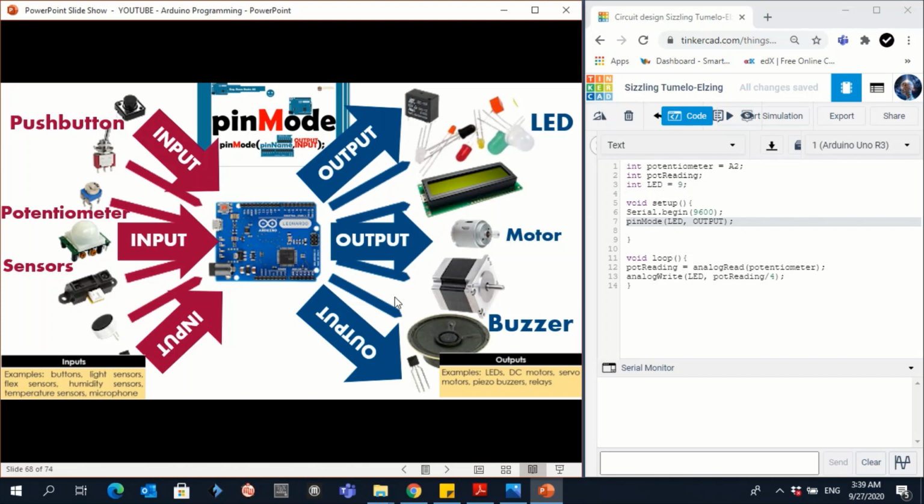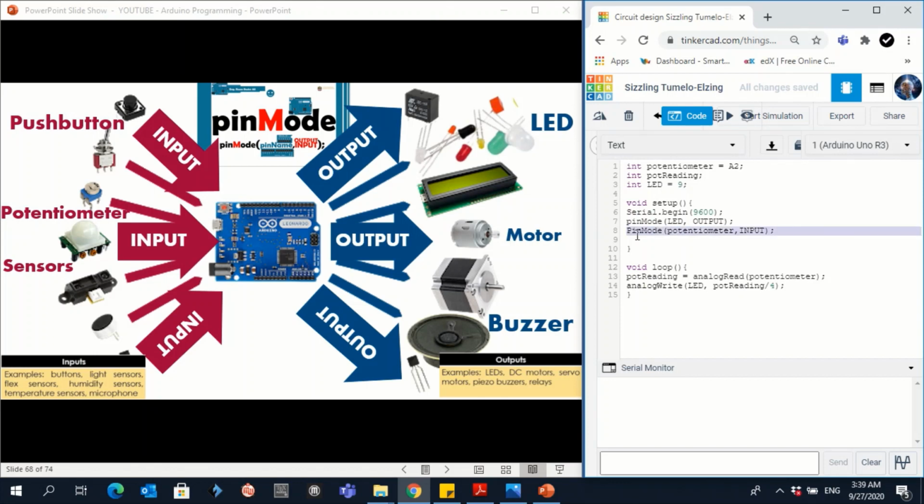are considered as output. So for the pinMode here, we have two connections, one for the potentiometer and one for the LED. In the existing code, you can see that there is a pinMode only for the LED. So why do you think that is? Why was this line not there for the potentiometer? The potentiometer of course is acting as an INPUT, and don't forget, all in capital letters.